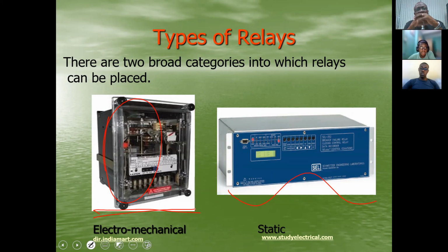And because of the flexibility of the burden impedance that you can connect to the CT, if you replace the high burden of the electromechanical with a static, you would not see much of a problem. You would still have much of the secondary current flowing to the relay, because the resistance on that parallel path is significantly less than the impedance of the core of your current transformer.